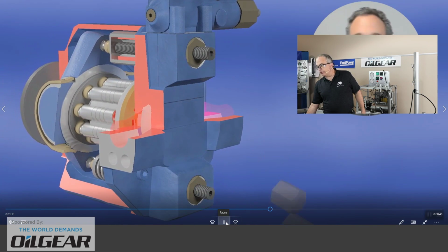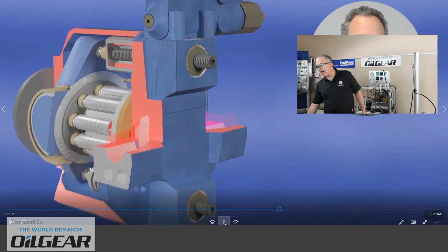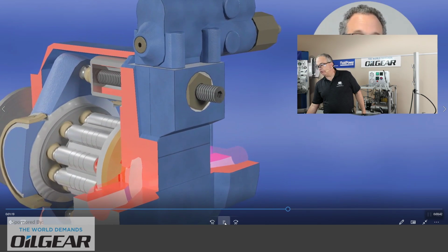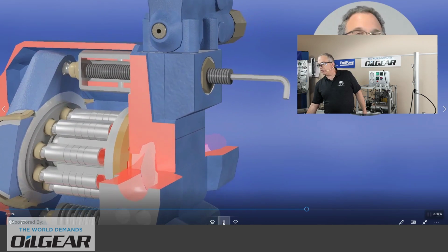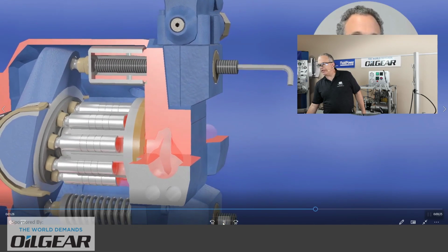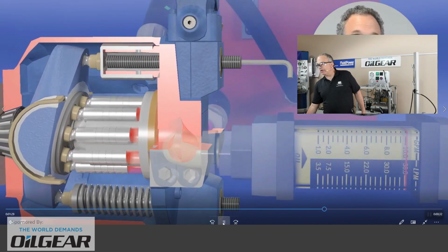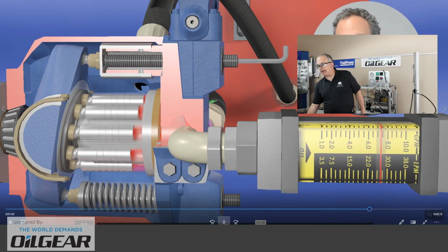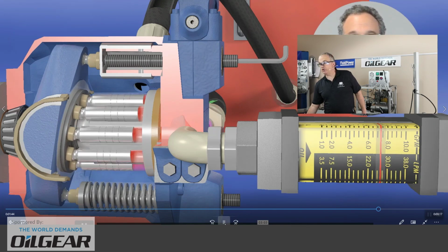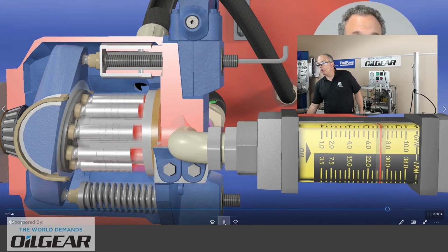Okay, a couple of other adjustments that you may or may not have on your pump. This one is called the maximum volume stop, sometimes referred to as Q maximum. Q, a common letter for describing flow rate. And this one is adjusted when the flow has an easy, unrestricted path through your system, no pressure loading. And if we dial that hex key clockwise, basically what will happen is we prevent that pump swash plate from ever reaching that 20-degree angle. Perhaps we're now at only 17 degrees angle or 15 degrees angle.